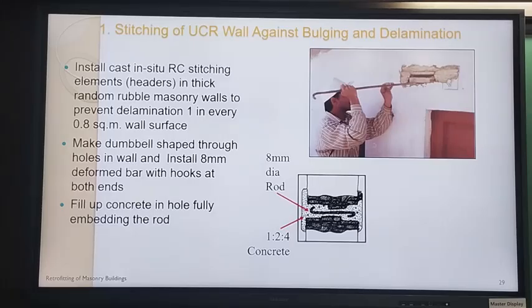Now, the way we figured out was that we decide first where things are to be done, we mark these places, if there's any kind of plaster, we remove it, and then we select a stone which is not very big, because stones vary in size. You can go 6 inches here, 6 inches there, it doesn't matter. And then we got these rods made with a pointed end.